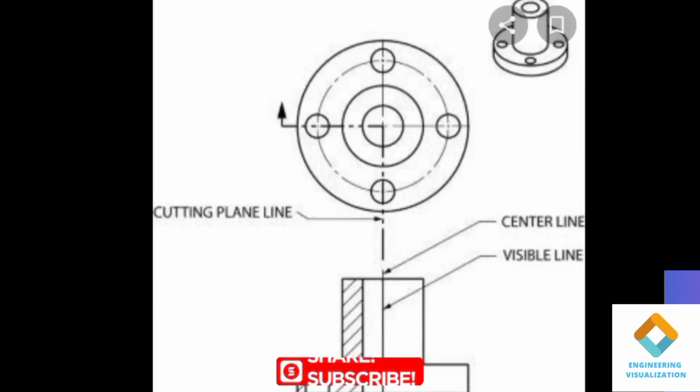A half sectional view is a view of an object showing only one half of the view in section. Symmetrical parts can be shown in half sections. The view obtained after removing the front quarter, that is one-fourth portion of an object, by means of two cutting planes at right angles to each other, is called a half sectional view. You can see clearly from the diagram there are two cutting planes at right angles to each other cutting the solid in a half sectional view.